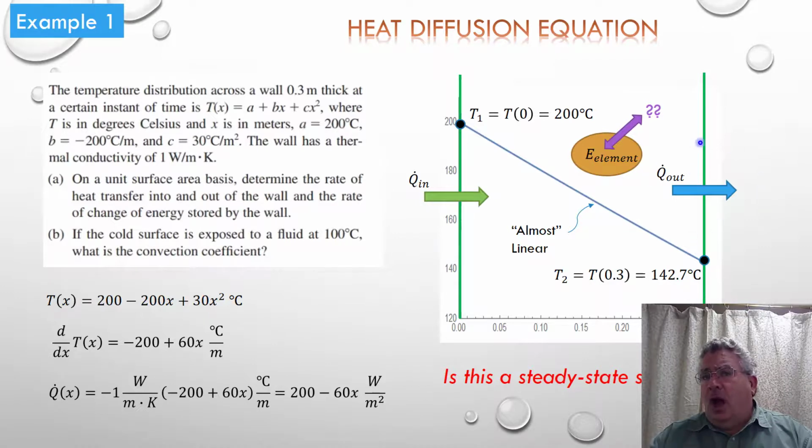I'm also drawing the heat flux on the right-hand wall as going from left to right. So in this case, I'm also assuming it to be positive, but a positive value for the heat flux at the right-hand wall means that we're having heat flowing out the right-hand wall. Which of course will make sense because look at the heat profile. We're expecting a heat profile where energy is kind of flowing downhill.